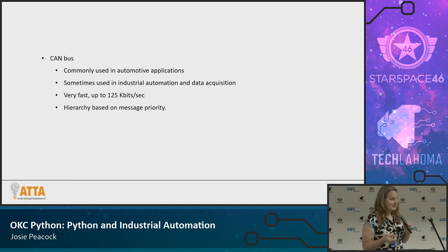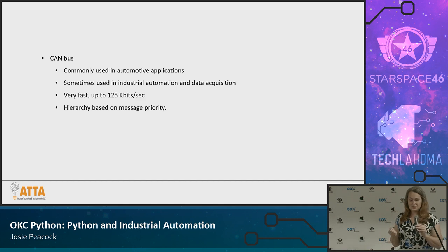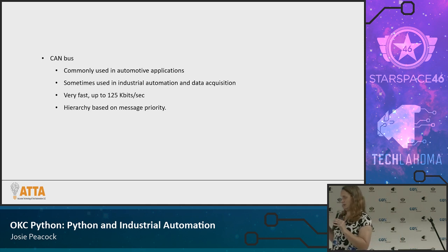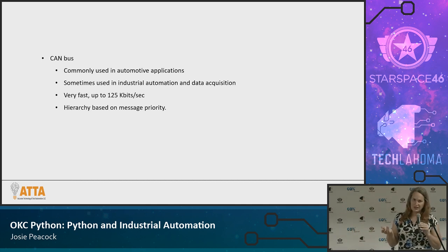But it's maddening because it's coming through in binary words, and you have to make sure that, depending on what the manufacturer felt like, it's least significant bit first or most significant bit first, and then get things flipped around right so you're actually reading good data when you come through.